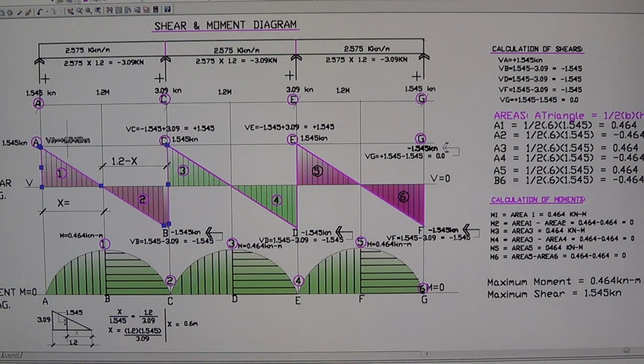Always go back to real. It is continuous, right? Think about that line is continuous. So we have a continuous purlin. So when you go to the next point, you have to consider the last one where you left off. Alright, so the shear at B here is the shear at C, which is positive right here, and then the negative, and along this area here you have to stop. There's a reaction there, so all we need is the load here. We're done with that. We are here at C, and then we're going to the D, right?